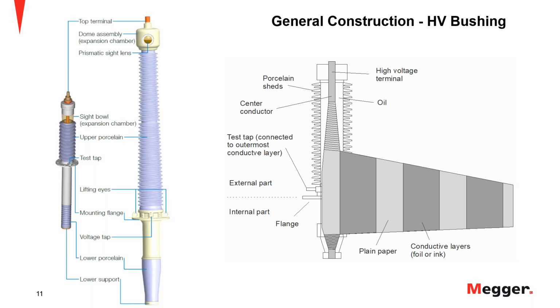This is created with electrodes, which are basically painted with conductive ink, or we have also some metallic foils, could be aluminum foils, of different lengths, which are inserted in this wrapping that we have for the insulation system for this condenser type. As you can see here in the design, we will see different distances creating these capacitors.